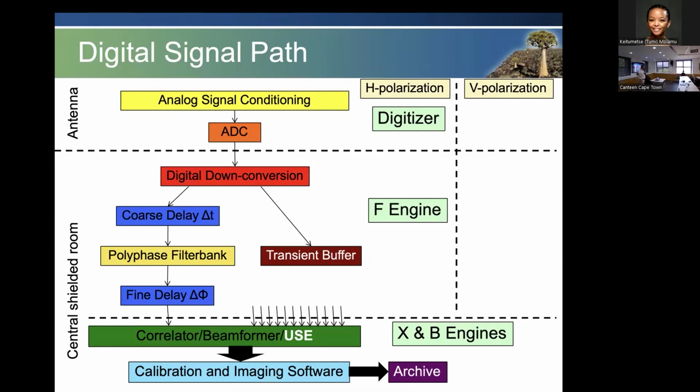You've got a fairly wide bandwidth signal, and the first thing you want to do is to get that into narrow frequency channels. And this is what we can do these days with modern radio telescopes. We've got the hardware to do it. And we saw in the previous lecture, one reason for doing that is that if you're looking at pulsars, they're dispersed. And if you look at the whole wide bandwidth, you're not going to see the pulsar. But you've got a half a chance of seeing the pulsar in each of these narrow channels. And especially if you know the dispersion, you can pile them all up, and Sarah will answer all the questions around that.